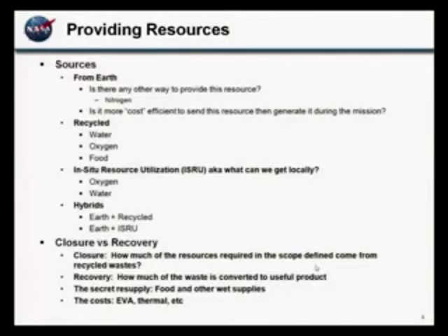When we've looked at analysis of the Orion vehicle circling the moon, when you're on the hot side of the moon, your environment is so extreme that you can't use a radiator successfully to reject all of the heat from the vehicle. If the outside environment is hotter than you want to be, you need to turn off your heat transfer.